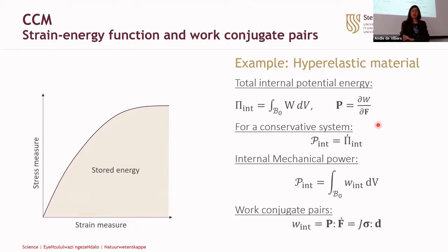Nonlinear elasticity. And you can write, this is a stress tensor called the first Piola-Kirchhoff stress tensor. You can write the stress tensor as the partial derivative of the energy with respect to the deformation gradient. So something that has to do with force, something that has to do with deformation. Okay. For a conservative system, the internal power